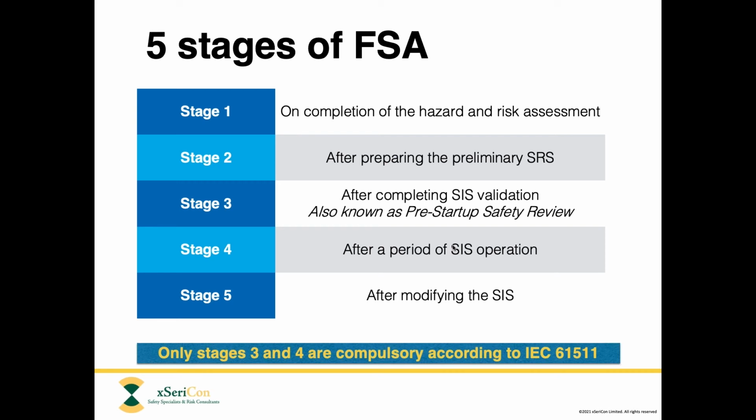The third one, functional safety assessment, which is the topic of our webinar today. This is a high-level review of the management system for functional safety to confirm that the overall safety objectives of the safety life cycle are being achieved. And that it should be performed at several different stages during the life cycle of the safety instrumented system, and we're going to explain that in a few moments.